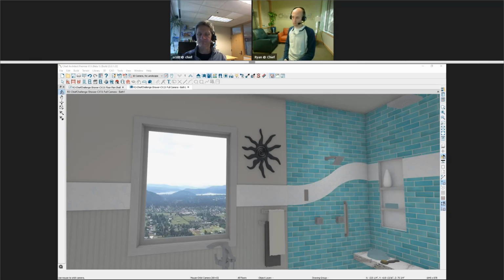So it's like if you were to imagine just taking that image, it gets stretched to fit on your monitor regardless of the angle that you have looking out your camera. So one thing that we do to trick the background sometimes is you can create a polyline solid or a surface outside the window that's important to show that view, and then you can map it to the solid surface instead. That way, when you're taking your camera angles and looking out the window, it's more of a static scene that you're looking at, instead of the program trying to map this arbitrary image behind your house.